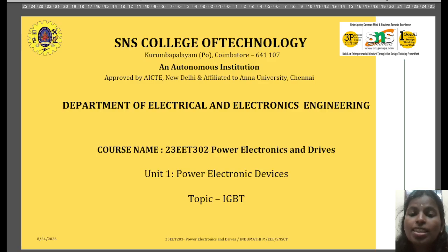Hello everyone. In this session, we are going to discuss IGBTs. An IGBT is an insulated gate bipolar transistor. The IGBT combines the best of both transistors, that is, it combines MOSFET and BJT: the high input impedance of MOSFETs and the low conduction loss of BJT. So it combines the best of both.